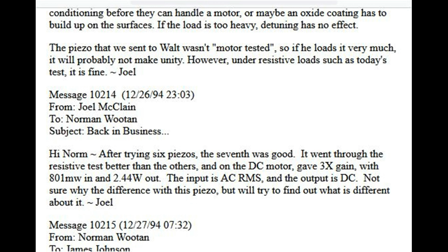It went through the resistive test better than the others, and on the DC motor, gave 3x gain, with 801 milliwatts in and 2.44 watts out. The input is AC RMS, and the output is DC. Not sure why the difference with this piezo, but we'll try to find out what is different about it.